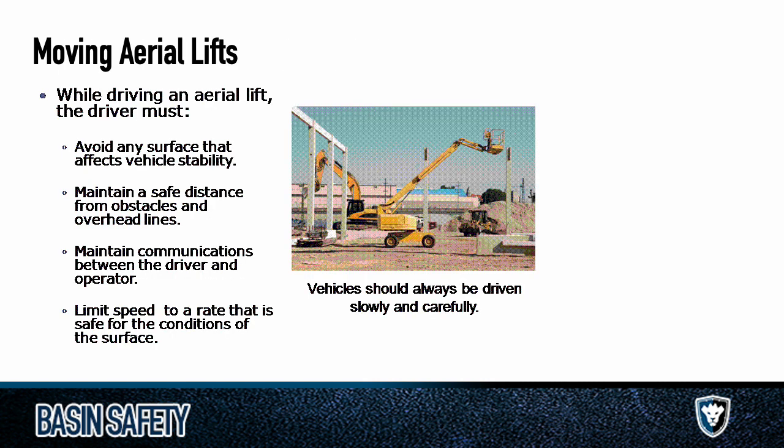Moving aerial lifts. While driving it, you want to make sure that you avoid any surface that affects vehicle stability. Maintain a safe distance from obstacles and especially overhead lines. You want guys on tag lines with the equipment, which we'll get into on the rigging side if you're lifting things. Limit speed to a rate that is safe for the conditions of the surface. And again, like I said before, low and slow. That's just the best rule of thumb.